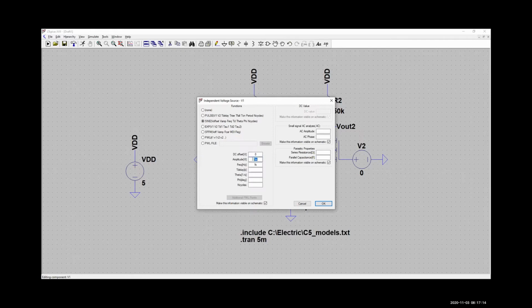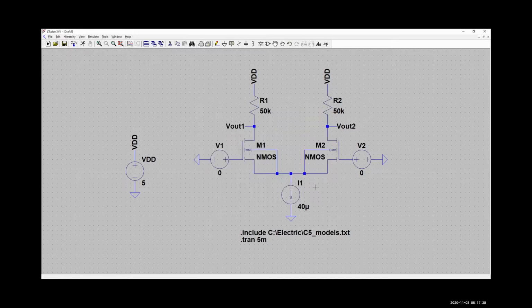And let me edit this to where this is simply actually grounded. So I have the circuit that we have drawn, right? The only real difference here is that I have explicitly tied the body of each of my transistors to not ground, but the source. And we might have to explore that in a moment.